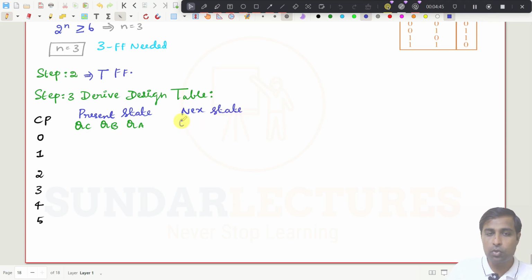So QC plus 1, maybe I will use the same green color, QC plus 1, QB plus 1, and then QA plus 1, right? That is the next state we need to find, right? So how many flip flops we have now? 3 flip flops, right? So what we need to do now, we need to write flip flop inputs.